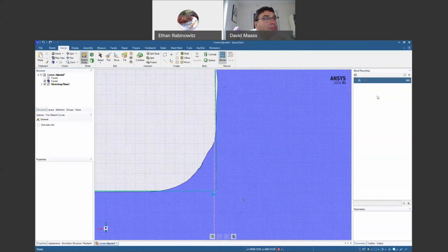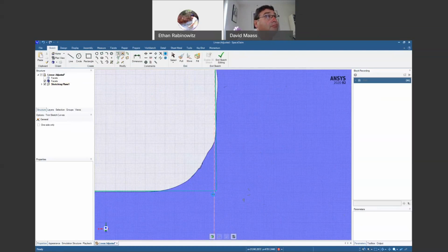It'll always be something you can modify. It'll just be listed out in a different step, whether we apply it at the sketch level or the 3D level. And both of those methods allow you to snap to the geometry. Like the pull tool allows you to snap the edge to the facets, and so do the sketch tools. So if we want to do it from the sketch level, create rounded corner, you essentially just click on the corner you want to round, and then the round starts to follow you.